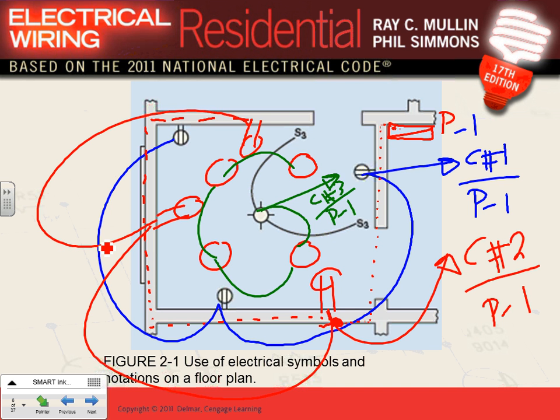So that's basically what you guys are going to be doing with Chad. Any questions, any comments? When we get into the derating, guys, we'll take this conductor that you're looking at, number 12, and we'll see when we do some derating, and you can see even if you derate at 50%, you're still pulling 15 amps out of that. So there's good stuff coming. Okay, so that's basically what you're going to be doing for the symbols. Any comments, any questions? Aaron, doesn't make sense?